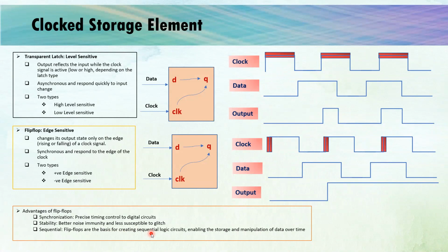So in summary, latches are simple and faster but lack synchronization. On the other hand, flip-flops have synchronization and are more stable but are also more complex. So they both are used based on their application only. Now with this, we'll move to our next slide, which is setup and hold timing.